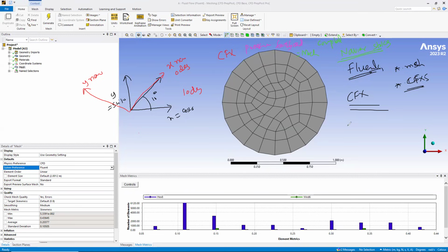But definitely if you want to go for OpenFOAM, this is a free software that you can download and use for free. The benefit is that OpenFOAM can have some solver features which are not available in CFX or Fluent. Why? Because somebody implemented into OpenFOAM some solver features, like a new turbulence model, that is not tested very well.